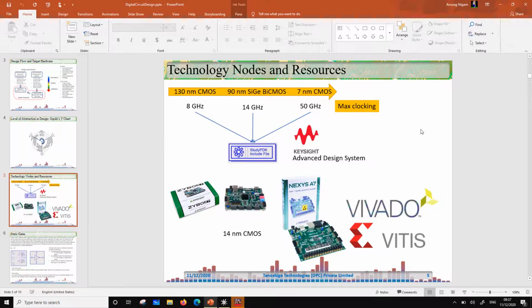Now going further, in this slide what I'm trying to show is everything boils down to, so all the circuits, no matter how complex they are, right, at the very low level of abstraction they are just transistors connected together, and the speed of the circuit basically depends on the parasitics like capacitances and the trace resistances, right? So there are delays involved in any digital design, and this is because of the resistances and the capacitances, right? Now as the device becomes smaller and smaller, these capacitances become smaller and smaller, and then these trace resistances become smaller, the density of the circuit goes on increasing.